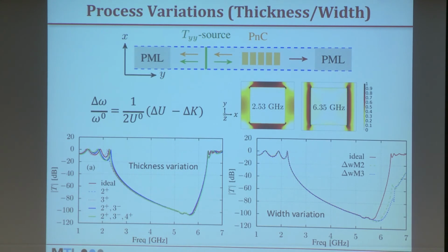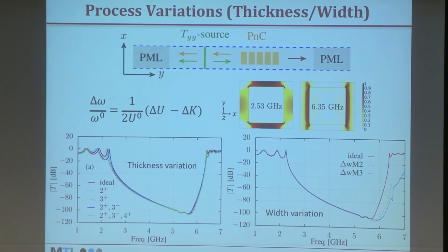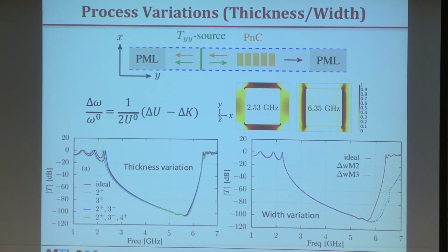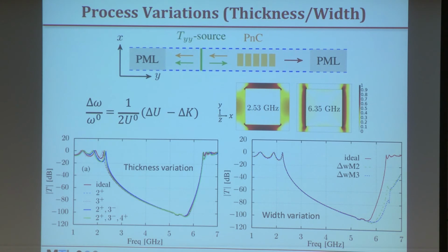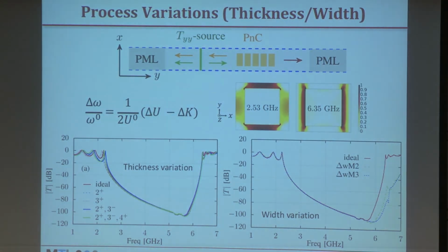So when I looked at how this perturbation in the phononic crystal affects the device, in fact, the effect is minimal. Why? Because most of the device energy is stored in the front end of line layers. And here I did lots of simulations, for example, to see how the phononic crystal is affected, and the effects happen at the edges of the band gap.